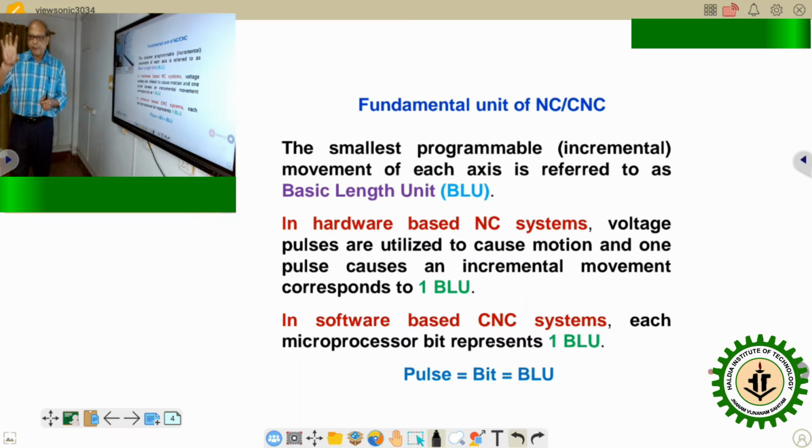So if the stepper motor rotates by a particular angle, say 1.8 degree, afterwards during derivation we will consider it as alpha, which is popularly known as step angle. So if the stepper motor undergoes alpha degree for one pulse, then what would be the corresponding rotation of the lead screw, where in between there is a gear train or gear ratio of Rg, such that Rg is greater than 1.